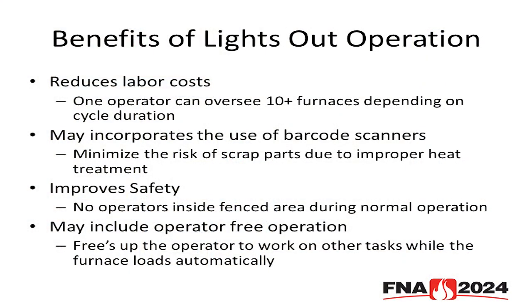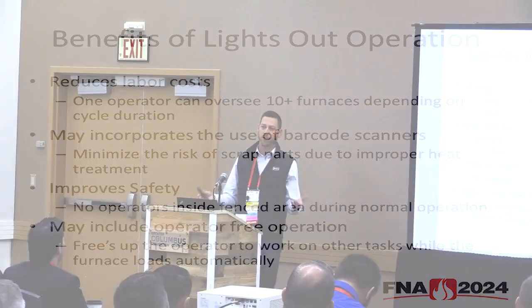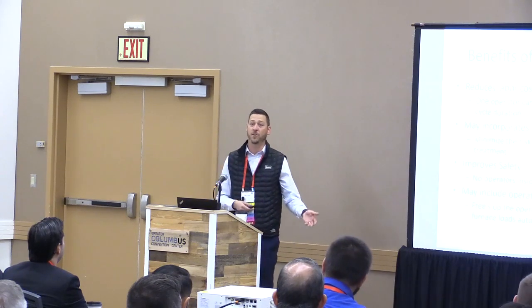One of the other big benefits, right, is that the furnace loader, as soon as a furnace is open, it's going to load that furnace. So you're never going to have furnaces sitting idle. As long as you have green parts that are on the tray tables waiting for the loader, the system's going to load it as fast as it possibly can. And this is where we see a lot of downtime with our customers that do have operators loading furnaces. You walk by and a furnace is sitting open, and you walk by an hour later and it's still sitting open. And you wonder to yourself, okay, why is that furnace not running parts right now?